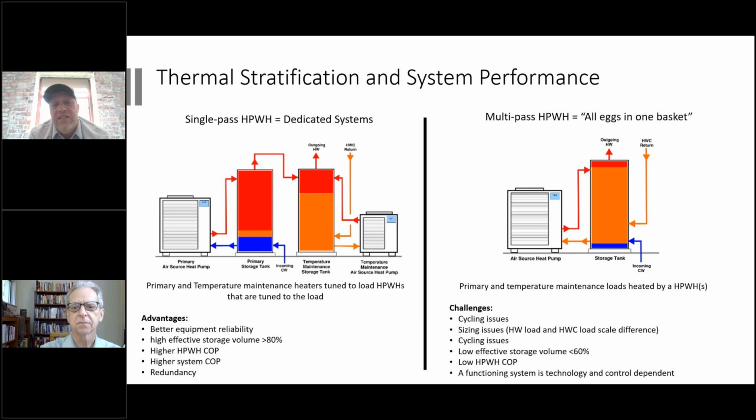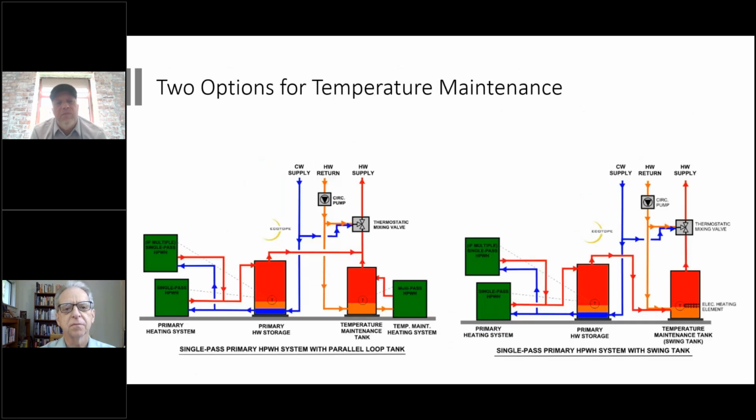And then the multi-pass, these are going to be cheaper ways to heat. They're very synonymous with gas boilers, how we've been doing those. Return everything to one big tank and out you go. I've seen these systems work. We've got a couple in our design, but with the recirc running through there all the time, your primary heat pump is going to be running pretty much 24/7, just because there's always flow going through it. And that can impact your performance too.